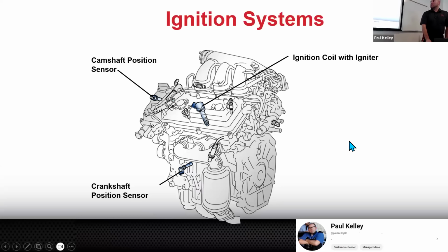All right, so now if you look at this again, we got 6 spark plugs. This part down here is secondary ignition voltage. But what about the small wires that go in there? What would you call those? Kind of gave it away. The primary, exactly. So on a coil on plug, if you need to test the primary voltage, it's not a really big deal. We'll test that with our meter, right? So there's some basic diagnosis we could do.